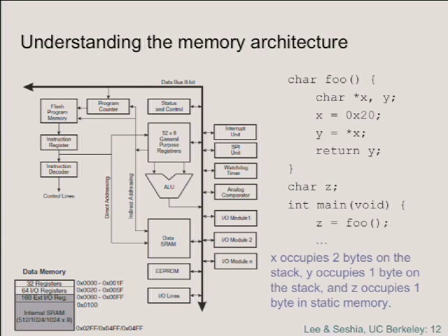But on the other hand, if the address that you're reading from is specified in a register, then a single 16-bit instruction word can specify the register, and consequently it becomes possible to execute that instruction in one cycle. But now that you mention it, I'm not sure whether the program memory in this architecture is 8 bits or 16 bits. If it is 8 bits, then yes, I think most instructions would take 2 cycles to execute. But if it's 16 bits, probably most instructions take 1 cycle to execute.